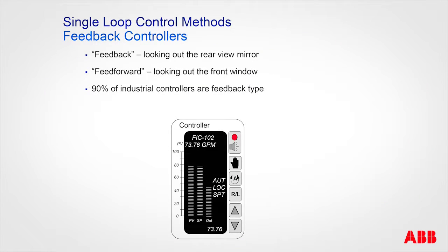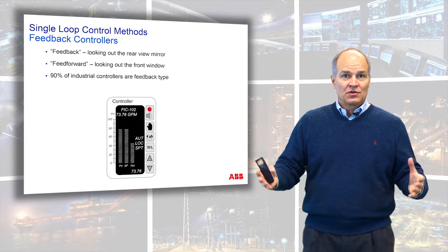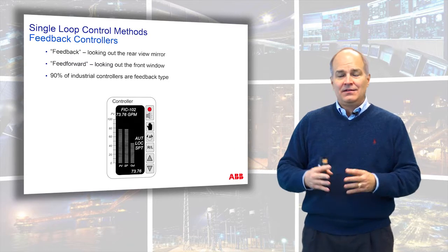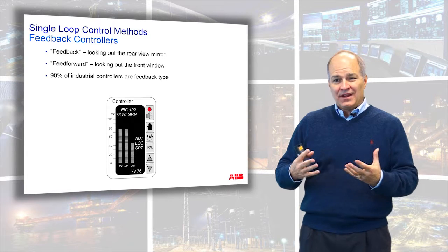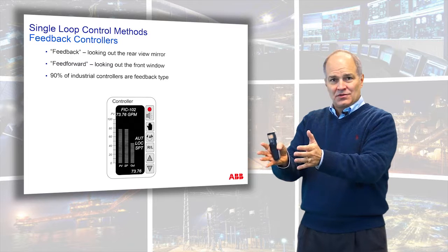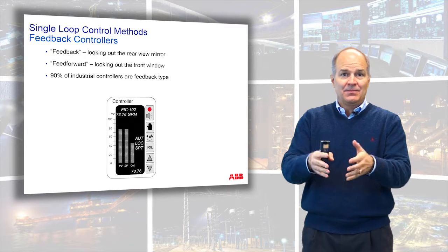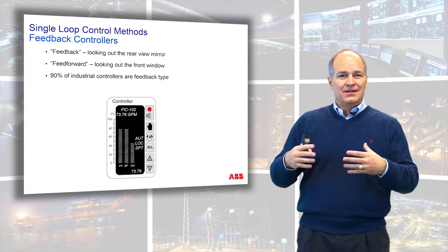90% or more, 95% of all industrial controllers fall into this PID algorithm. Yet it's one of the most misunderstood areas that we have. If you look at the history of where controllers came from, the different industries, there's a lot of different forms of the PID, a lot of different tuning parameters, different units, and quite frankly, you could be very good at one controller or manufacturer and then change to another one, put the same numbers in, and blow something up. So it has given tuning and controllers kind of a bad name.